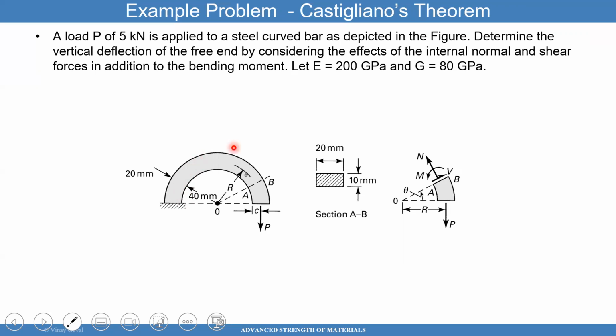Here you have a curved beam, and I apply a load P. All you have to do is the same process. Do a cut arbitrarily. If I do a cut there, I get a shear load. I get a force that's normal to that section. And I get a moment there. So if you take moments about that point O now, that shear force goes through the point O, right? True? So does that shear force contribute to a moment? No?